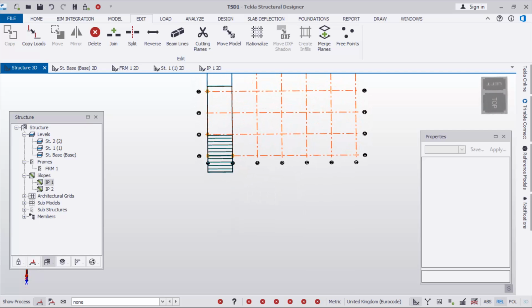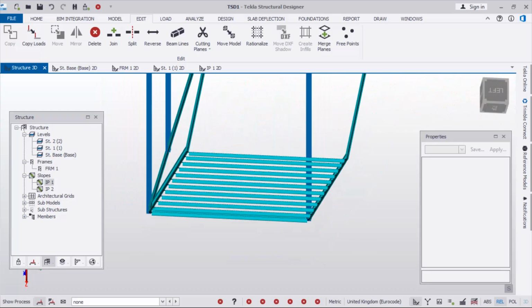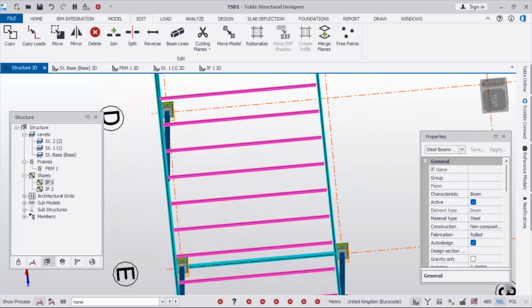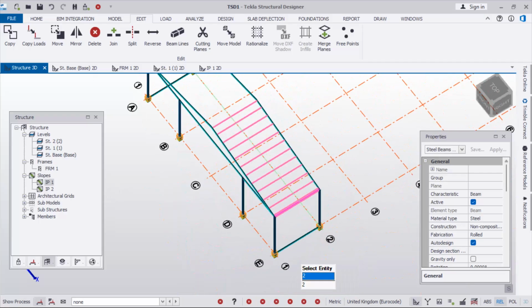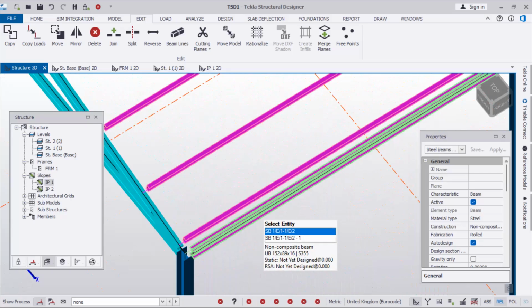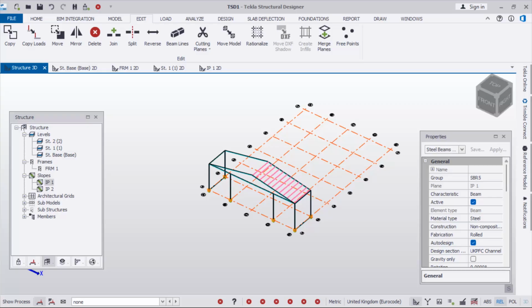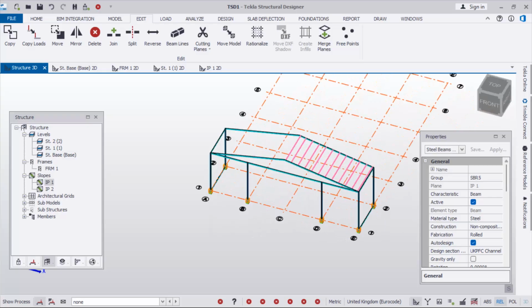So just come here like that, and then select like this, and then rotate, and then just come here, press Ctrl, then you uncheck that, and then after this you're going to mirror this on the other side.